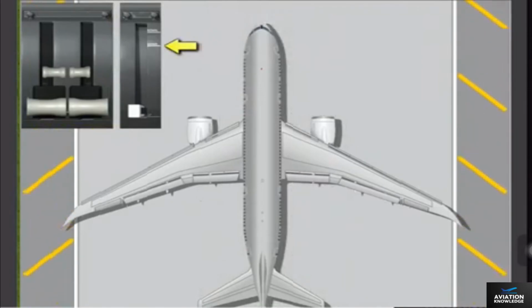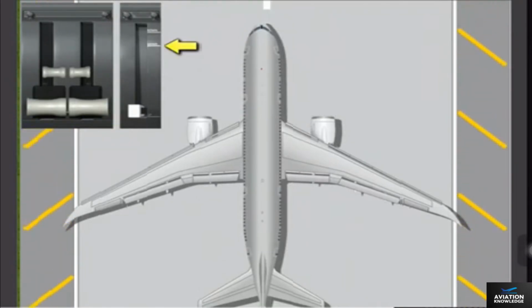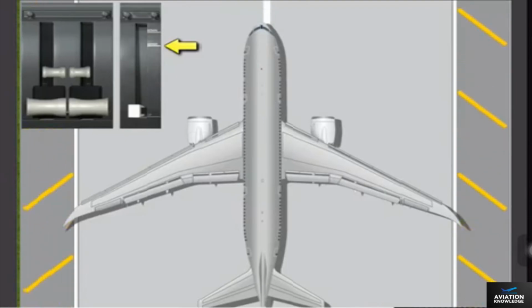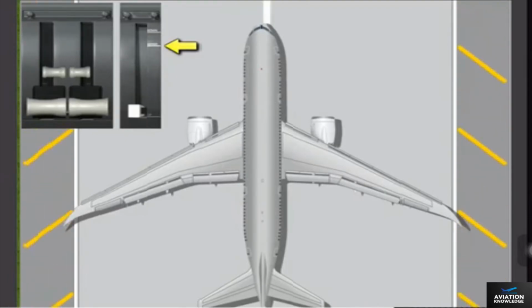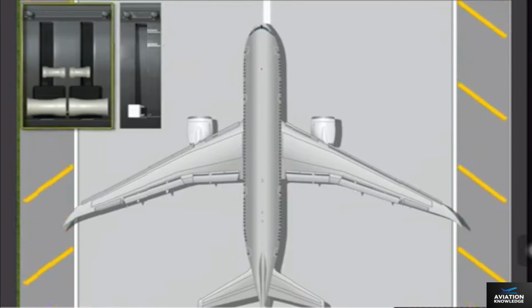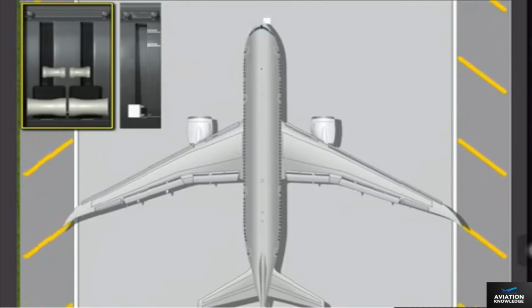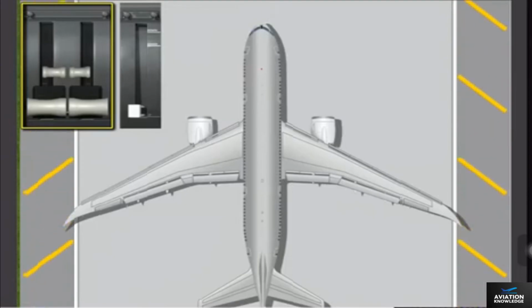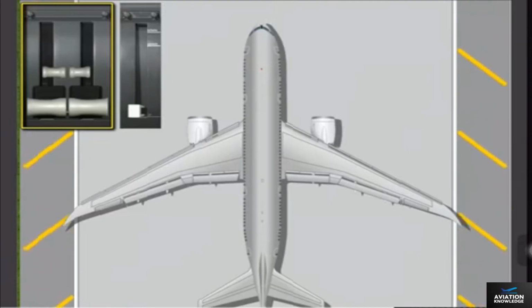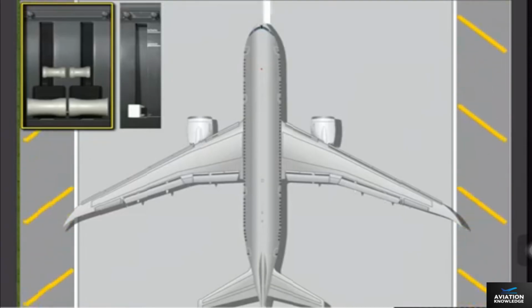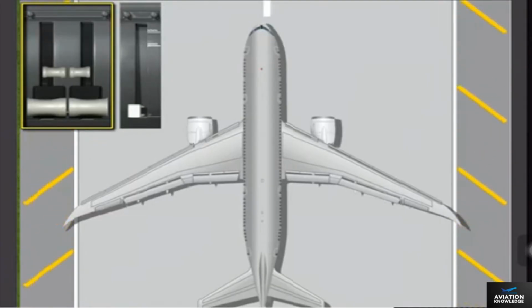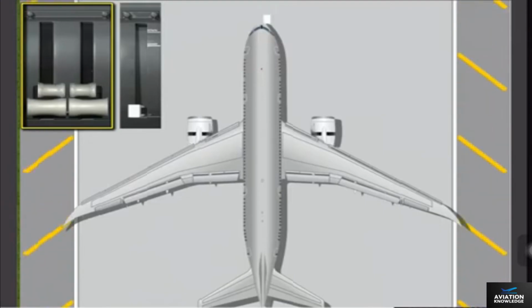When the speed brake lever is not in the armed position, the spoilers still automatically extend and the speed brake lever is driven to the up position when on the ground with ground speed above 85 knots and either thrust lever was previously in the takeoff range before both thrust levers are moved to the idle range, or on the ground and both thrust reverse levers are moved to the reverse idle detent.